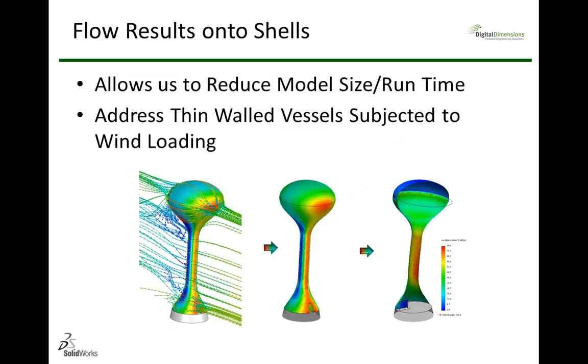Another very nice aspect to an improvement with flow simulation is that now we can analyze shell models created in SOLIDWORKS inside of flow simulation. In addition to that, we can export these results and apply them to a shell element inside of a FEA analysis. The performance boost for this is huge. We no longer have to worry about creating fully contained models. We can now represent models with simple shell elements, get the CAD data out quickly so that we can analyze the design efficiently. Let me show you an example.